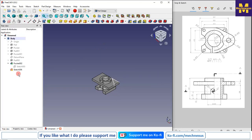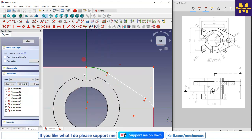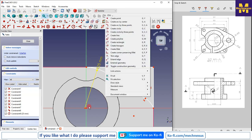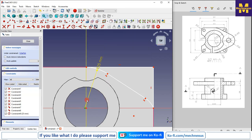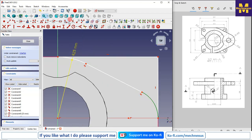So now I will constrain it. So I will select this and this. So I will give it radius 25. Make it coincidence, and I will make this and this coincidence, and this is the R12.